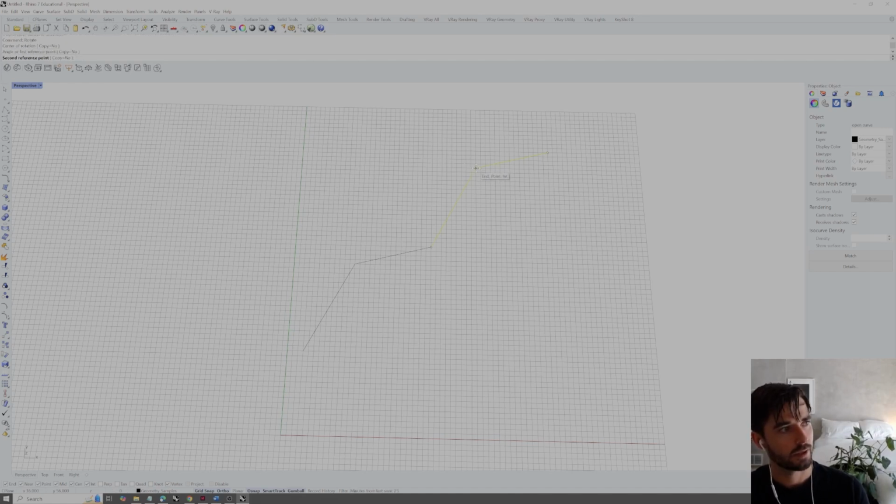So I'm going to click to reference that point. And now by default, we're snapping to orthographic rotations. So I'll just snap all the way down to -90 degrees, not the angle of rotation, -90 degrees, but we're snapping so that the line is oriented relative to the y-axis.